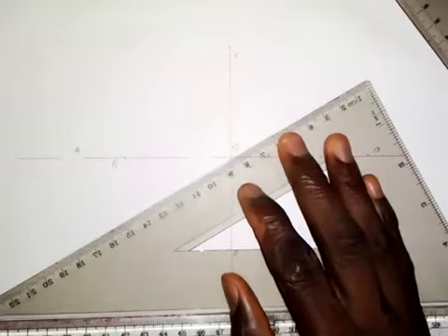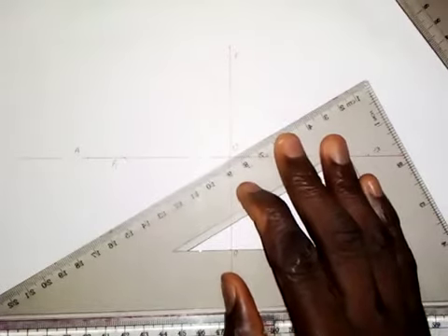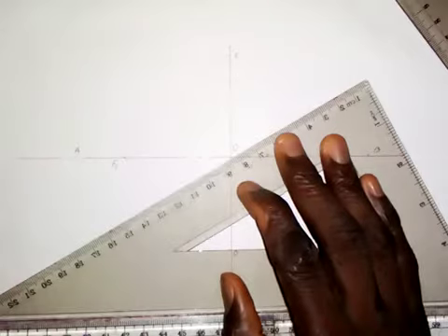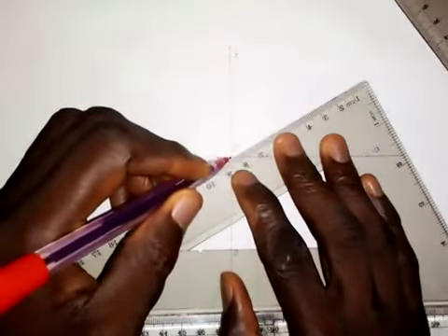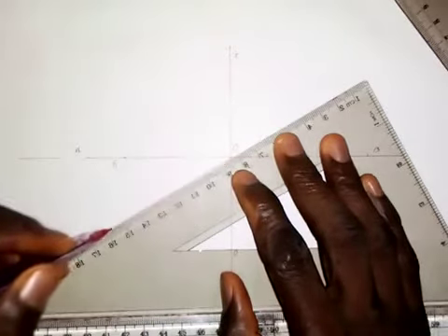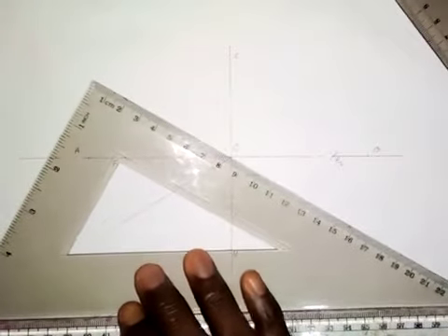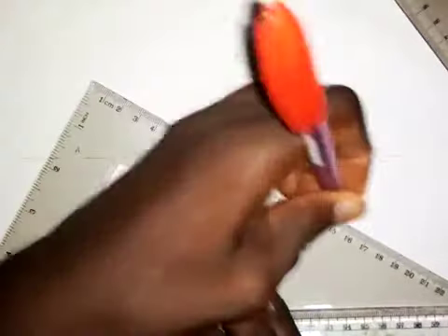That's why I said that everything that you have been taught in technical drawing is not a waste, is not lost. So we are still going to make use of them several times. So we continue making use of division of line to a number of equal parts in technical drawing. So we are going to draw a line in this direction also. So we turn our set square to this side. So we also draw a line in this direction like this.